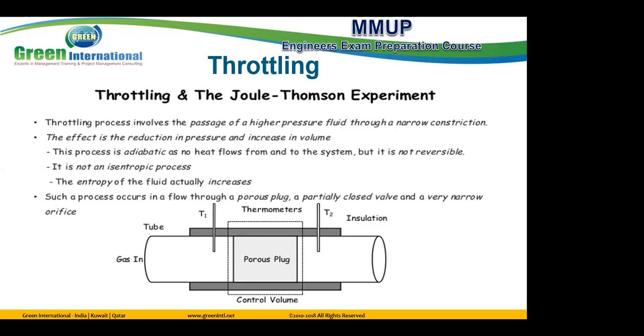The process from 1 to 2, high pressure to low pressure, does not go back from low pressure to high pressure again, if passing from the backside. So this process is not reversible. It is the same as two gases with a diaphragm in between that mix and can't be separated again. So this process is not reversible.